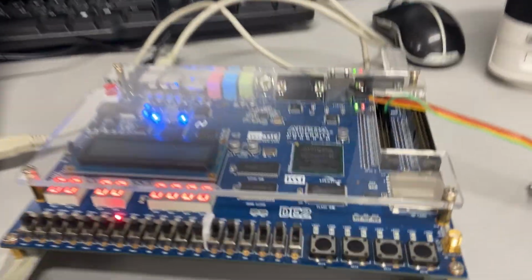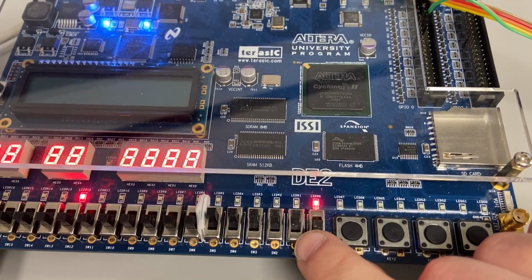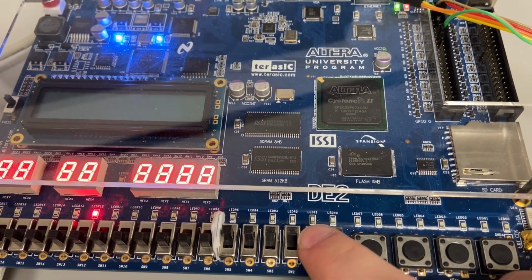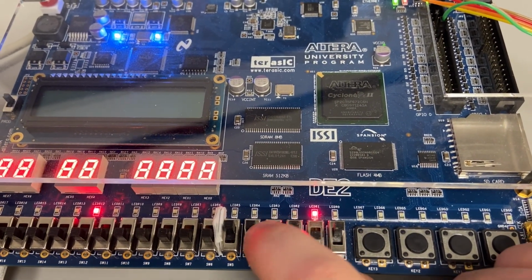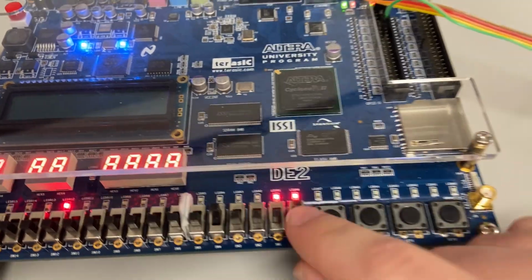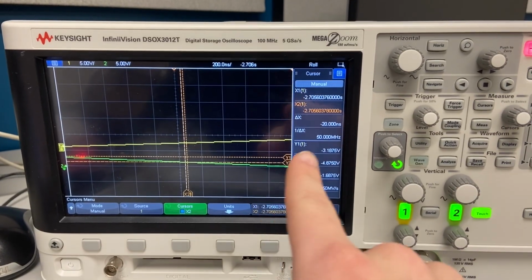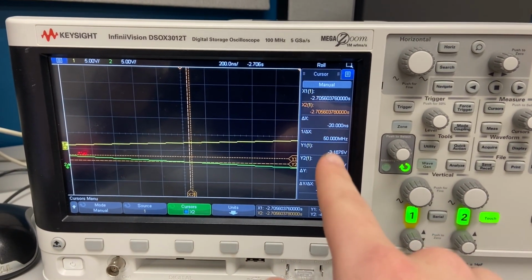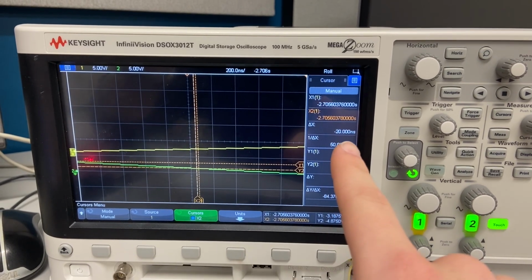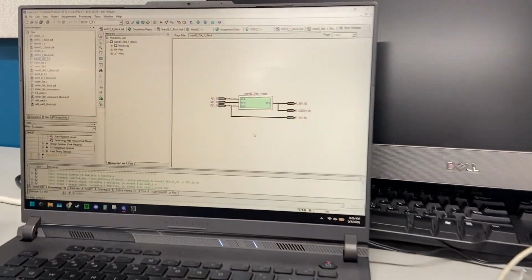And if we move on to the hardware testing, then we can see that all of these are high, so they're low. If I change any bit down to 0, then it correspondingly goes high. If I do the same thing for this bit, it does so. If I drop any of these bits, it follows. And then over here, we can see the time delay on the oscilloscope reading 20 nanoseconds. My memory is not good enough to know if this is the same or greater than the non-component form, but you'll know if you read the PDF. And that's it for this circuit.